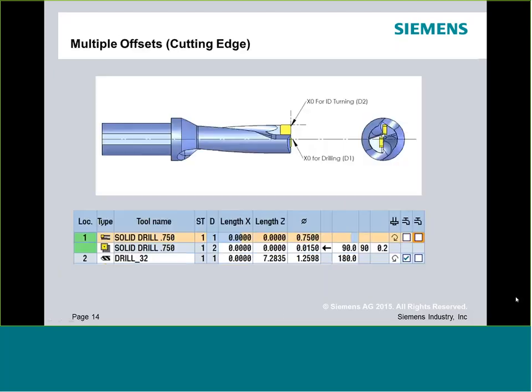Now, when we get to drilling, there's certainly two different types of drills that would be the most standard types of drills. You get twist drills, right, with some type of an angular point, 118, 130, 140, you know. And then we have an insert style flat bottom drill. Now, what is nice with the insert drills is there's a couple of tricks that you can use.